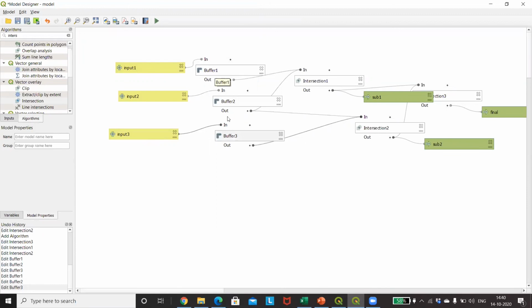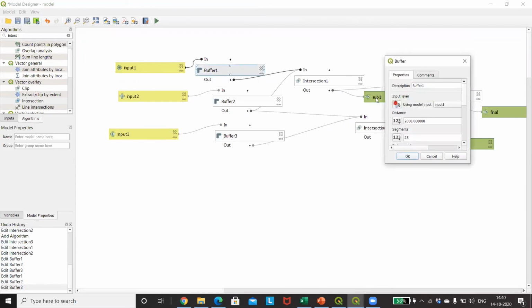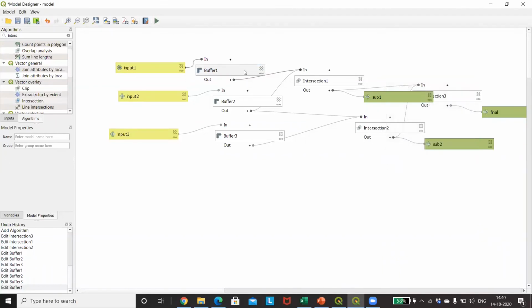I'm building a buffer of 2 kilometers around each point, that is a flat, school, or a hospital, and then finding the intersection of a flat and the school and flat and the hospital, and finally finding the intersection between these 2 points, so that I get a flat location which is having within 2 kilometers a hospital and a school, which are essential while deciding any location.